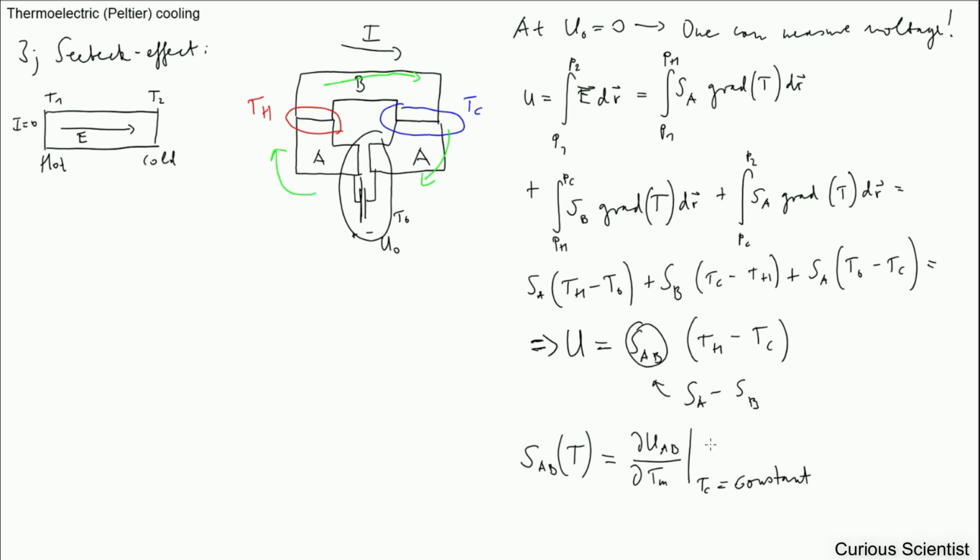So for example, you cool down your device to -20 degrees, then you switch off the power supply and start to measure the output voltage from your device, and at the same time you measure the temperature, and you will be able to plot this.